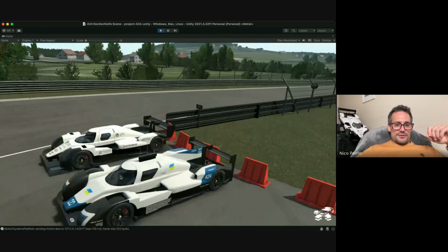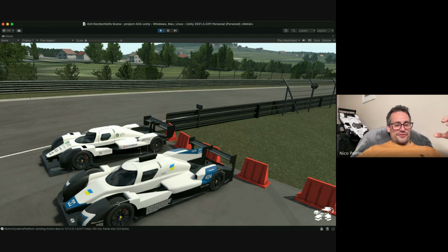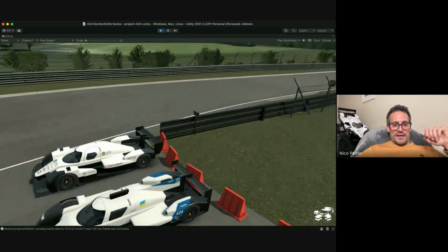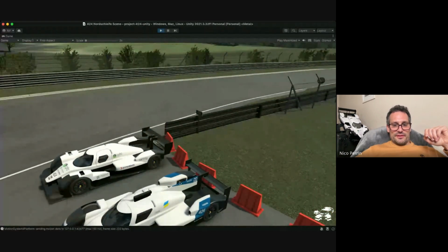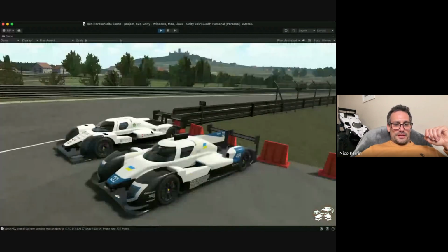The last thing is you see these big holes on top of the front wheels for Le Mans. They're smaller here. They're creating drag, and they're here for safety in terms of if the car goes into a high-speed yaw situation, and to avoid the car from taking off from the pressure under the wheel arch, Le Mans is asking for these holes to be there. There's also some at the back on the sides. We don't have them for the Nürburgring lap.